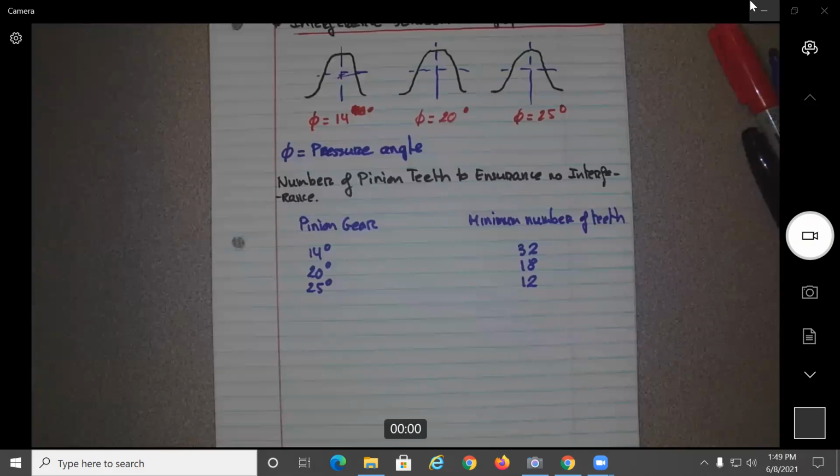that if your front sprocket is not perfectly aligned with the back one, the chains are really strong, but they're not really good at sustaining a lateral force. Rubber is a lot better for that. If you look at most of those custom motorcycles, what do they have? V-belts, because for a chain to be good, you need a very good alignment, so you probably need some more engineering.